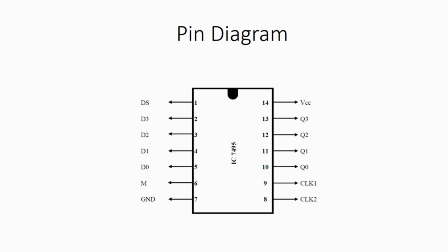The shift register is a sequential circuit wherein upon the occurrence of each clock pulse, the contents of the register are moved either in the right direction or in the left direction. This working can be realized with the help of the IC 7495. IC 7495 is basically a 4-bit shift register which is capable of shifting its contents to the